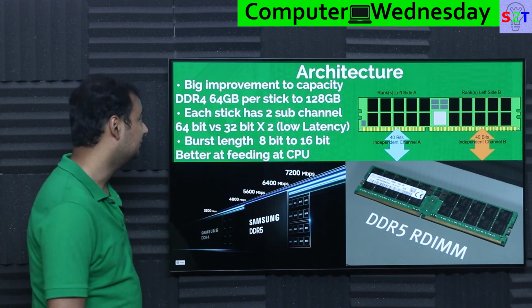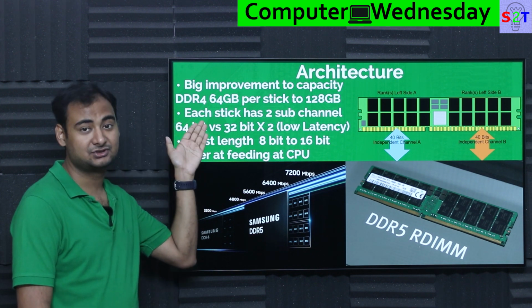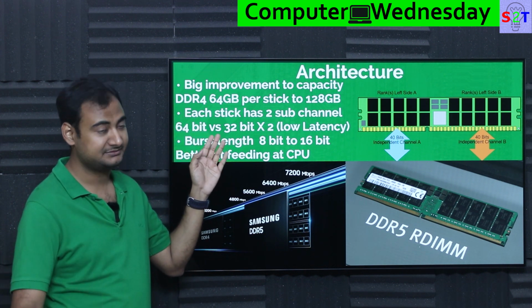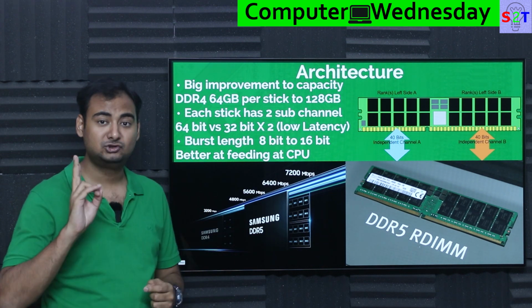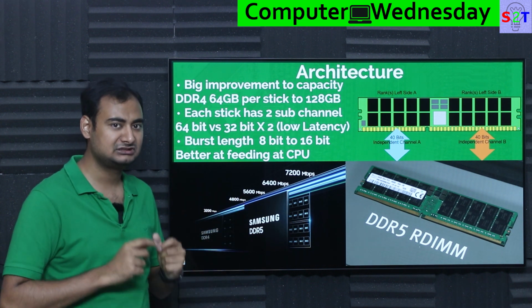What about the architecture? Now, in terms of architecture, just double everything. The improvement went from 64 GB, which I'm not sure anybody actually bought as a 64 GB kit, it was ludicrously expensive, so DDR4's maximum will go to 128. A significant enough upgrade. And each stick will have two sub channels. Be mindful, it's still not technically dual channel, but each channel has two sub channels inside it.